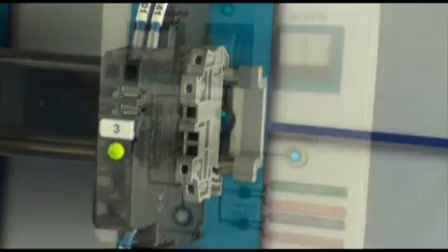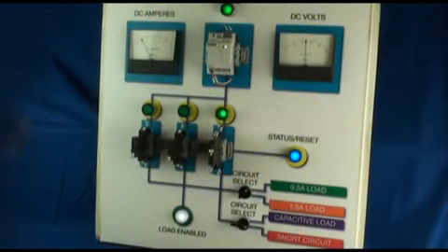We will now apply the short circuit condition to the ECE electronic circuit breaker. You will notice on the amp meter that the current does not go above 1.8 amps. This is the current limiting feature of the ECE. You'll also notice that the ECE breaker will trip before the power supply goes into shutdown mode.